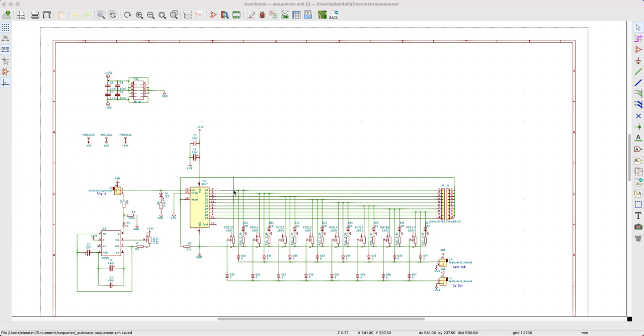Each pulse is used to form a control voltage with a potentiometer. Of course, a potentiometer is a voltage divider. We take the center pin off the potentiometer and send that to a CV out. Each potentiometer output on each individual step of the sequence needs to be insulated from the other ones.